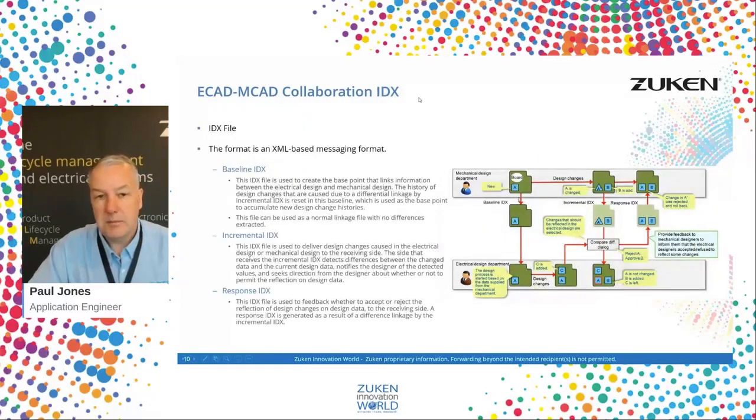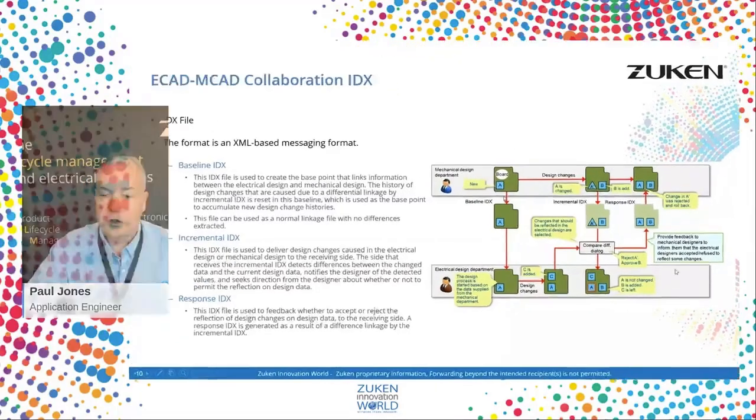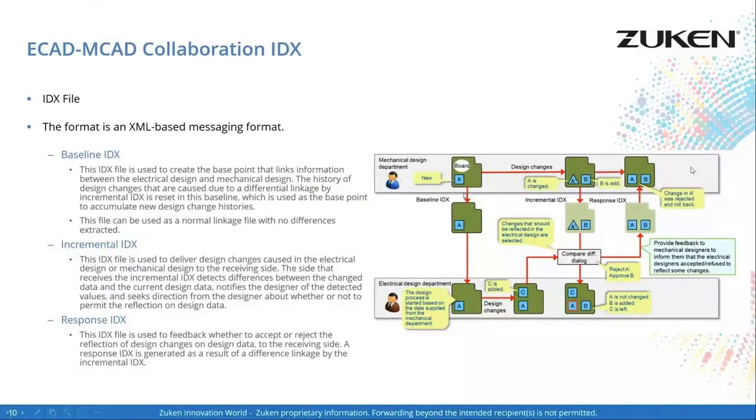So just moving from STEP onto IDX. We can see it's an XML-based messaging format, IDX. On the right-hand side here, we've got two different design flows showing how this fits together. The mechanical design team starts an outline, maybe some cutouts or some components in certain areas of the board, and transfers the data through to the hardware team or the electrical design department. This is then used as the base or the starting point.